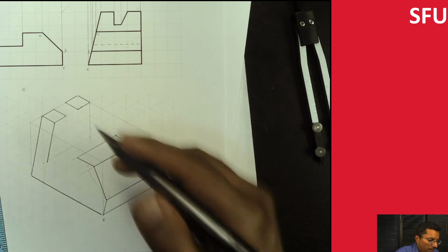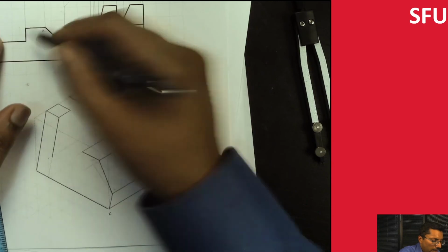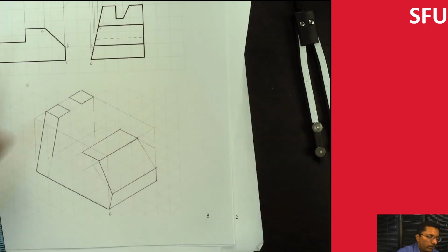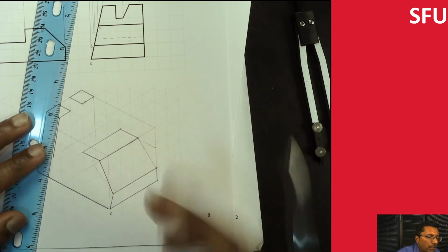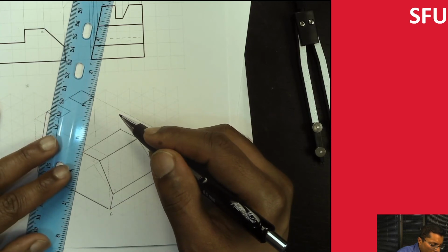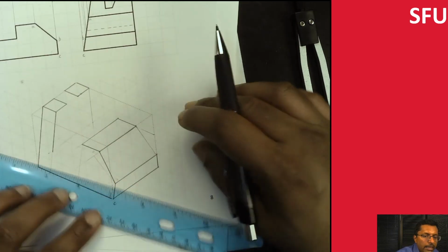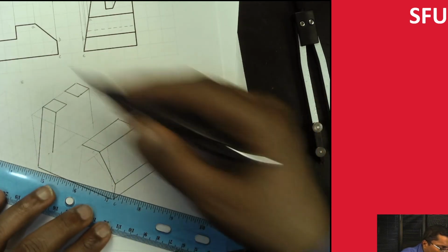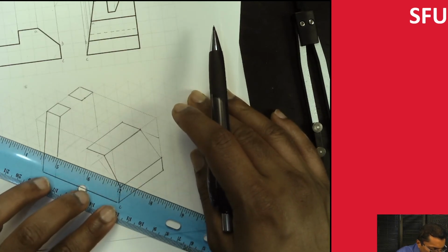So we look at it further, and in multiple views, this line and this line seem to be parallel. If the line is parallel in multiple views, then the line is indeed parallel. If it's parallel only in one view, and it's not parallel in the other view, then the lines aren't actually parallel. So we go from here, and we draw our so-called parallel line, drop it down, and then we look at this. And we can draw this to be a horizontal line, which would be parallel like so.